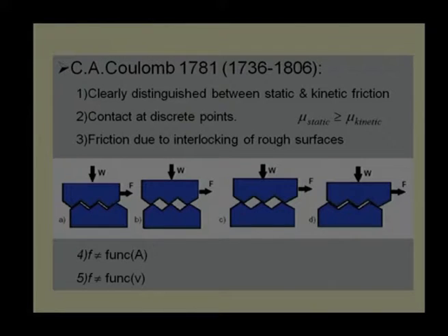Coulomb also mentioned that friction force does not depend on the area of contact. Another interesting point pointed out to Coulomb was whether the coefficient of friction depends on velocity or relative velocity, because of the model he gave. When you are pushing over the rough surface, it takes slightly more time from a stationary position, but in running condition the component will not fall back to the complete depth, it will be at a partial level. That is why the kinetic coefficient of friction is lesser, as suggested by Coulomb, but this also depends on velocity. If we say you push the component harder and harder, the coefficient of friction should be reduced. But Coulomb did some experiments, and based on that he concluded that the coefficient of friction does not depend on velocity. There is only the initial static coefficient of friction, and once it starts sliding, there will be only one kinetic coefficient of friction. It is not going to continuously reduce with velocity.